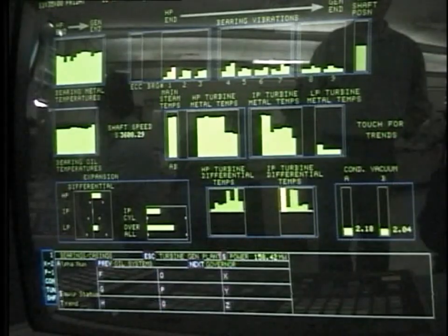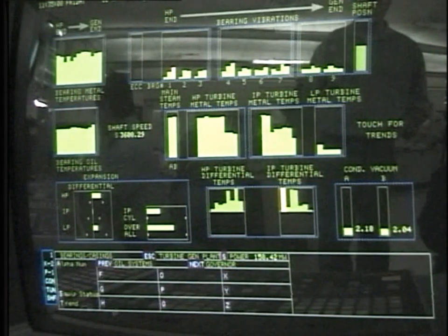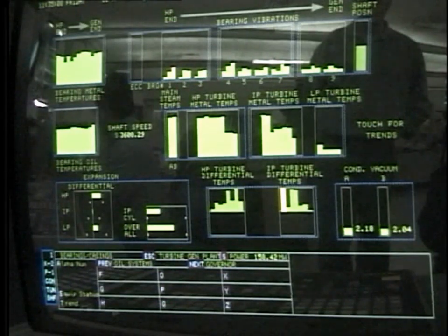These temperatures are usually recorded to give the operator guidance during startup. You must make sure to learn and remember the limits which are established for each of your turbines. In order to increase the output of the turbine, steam flow is increased, and this consequently adds more heat to the metallic components, causing expansion.